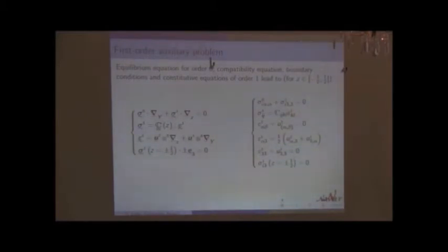Sorry, and you have a contribution also in the strain. You have a preload really coming from the strain, but this is quite the same feature as in the previous auxiliary problem. So this is expressed directly as a function of the indices. We already know that the in-plane U1 alpha will be 0 because it's in-plane displacement, and at this order, this guy vanishes. We already know that it is 0. And the unknowns are U alpha 2 and U3 2. Okay?